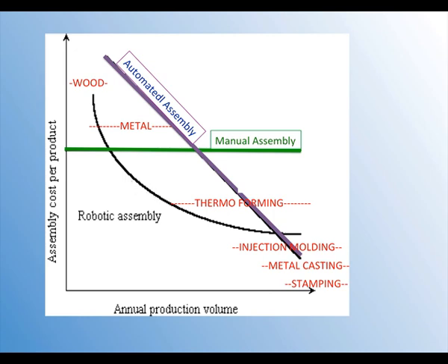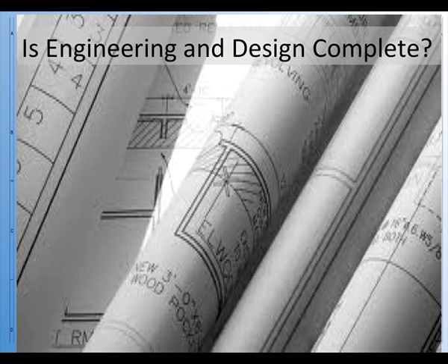Now, really critical to your RFQ, because you're going to be required, or you're going to want, to provide a design to the suppliers with the RFQ. And the question for you is, is engineering and design complete? If it's not, don't issue the drawing, and don't issue the RFQ, because the RFQ will be incomplete. If engineering is looking for supplier inputs to the process before completing the design, there are ways of doing that. That's typically what we call an RFP, request for proposal, or an RFI, request for information, not an RFQ.